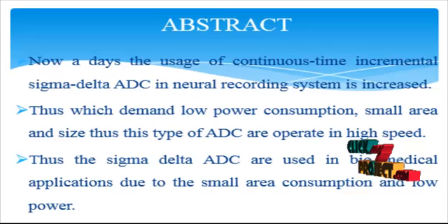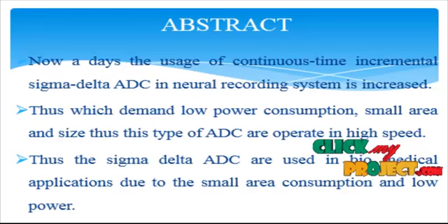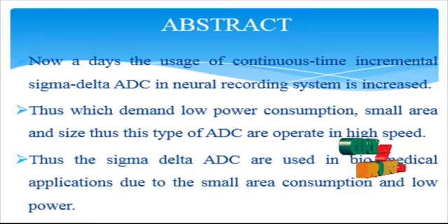By employing a high-resolution ADC, this requirement can be much relaxed, and several power-hungry signal conditioning blocks, for example the additional gain stage and the active anti-aliasing filter, can be simplified or even eliminated.